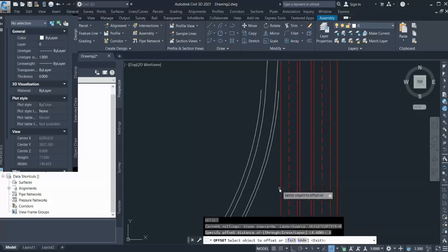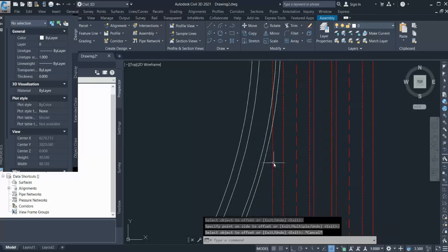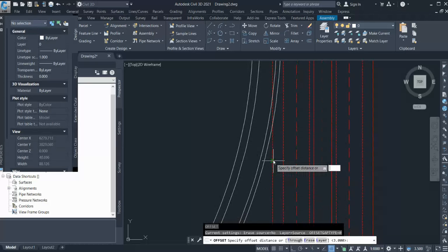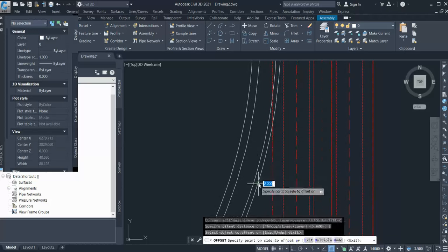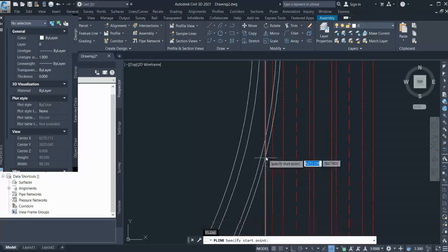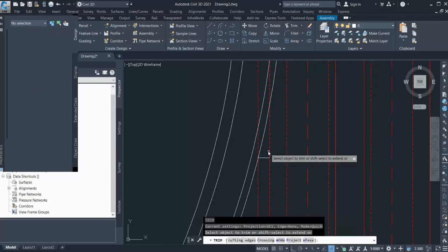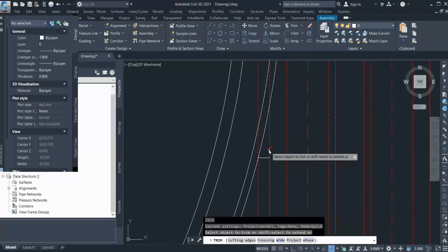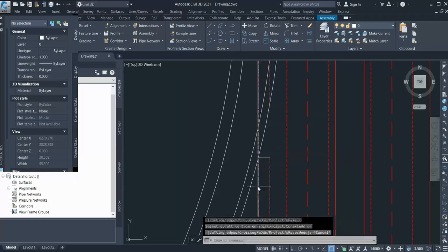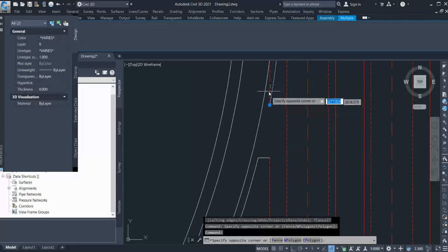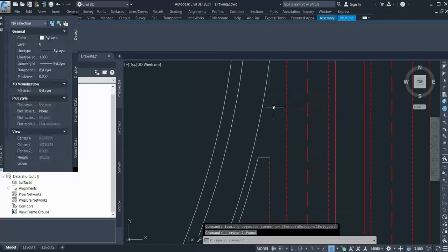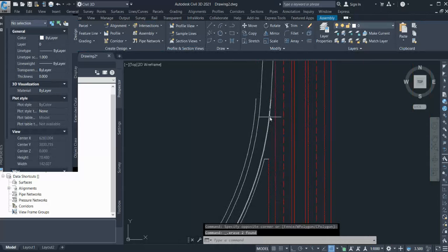Your main line would be a hard shoulder 3 meter, and now in this case I will check when I get 1.2, at least 2 meter. So somewhere here, so I'll just delete this. So between both hard strips, at least I get 1.2 meter gap. So just delete the rest of the lines. This is your nose area done.